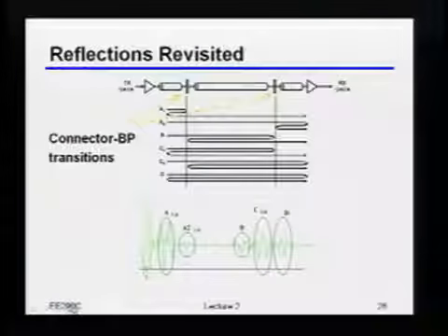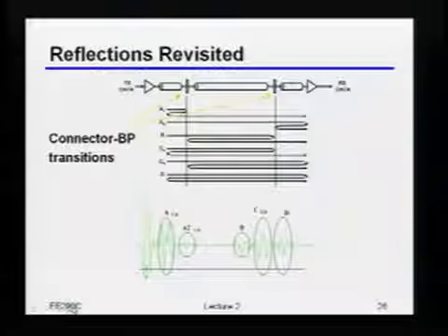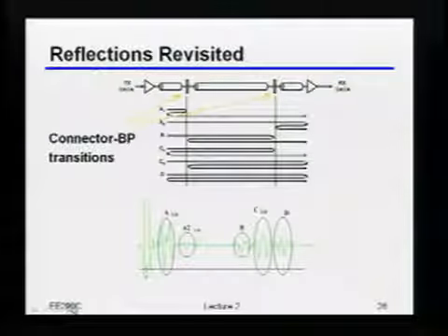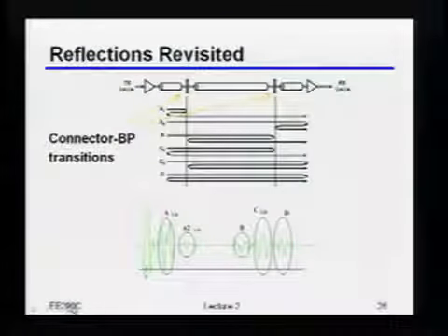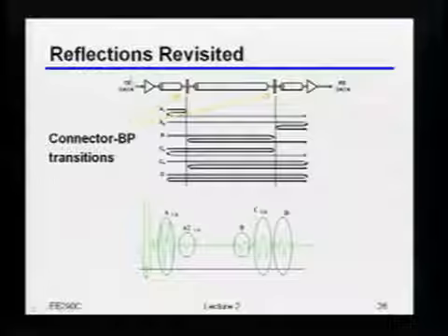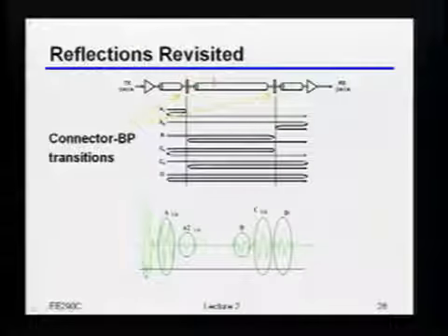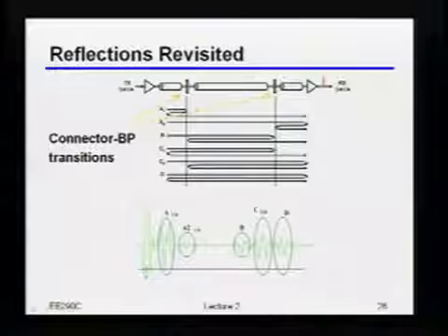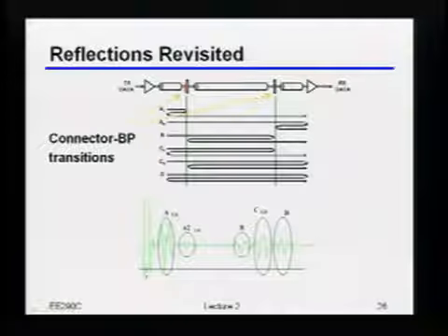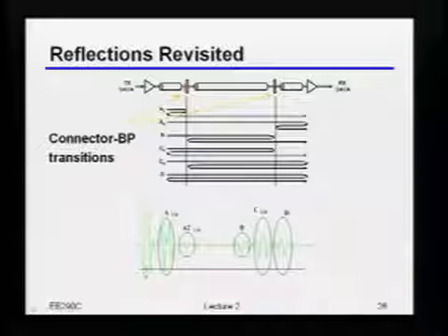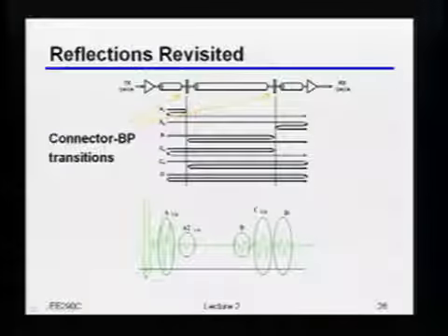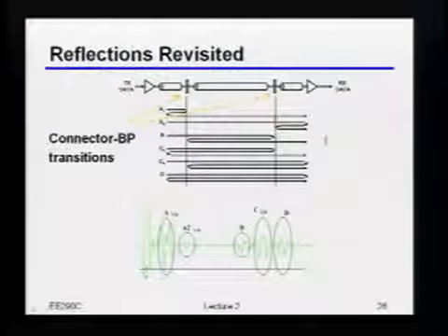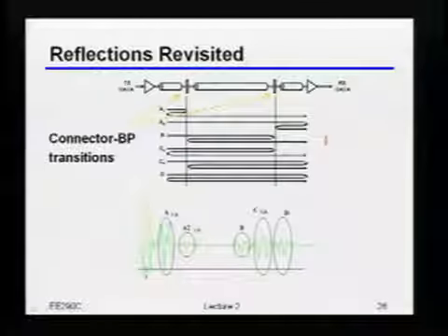So this is just another, let's say, fun view of those reflections. You'll actually be getting another view like this in your homework. This is just, again, to tell you, I said those connectors are really annoying. If I've got my daughter card going through the connector, through the backplane, through another connector and back, and those connectors are sources of reflections, I can have all kinds of these fun bounce diagram things, right? Because I go through, I hit that connector, I reflect back once. I have perhaps another one in this direction, which will reflect back and cause crosstalk, and so on and so forth.